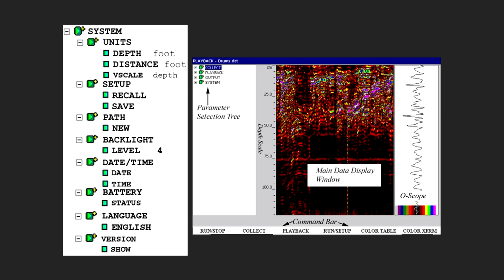If you see the screen, this is what it will look like. This is the first stage, and first of all we need to be very careful about the wiggle we are getting here, also known as the A-scope. It should not shoot up outside the range. If such shoot-ups occur, then we should try to reduce the gain, or change parameters such as the dielectric constant.